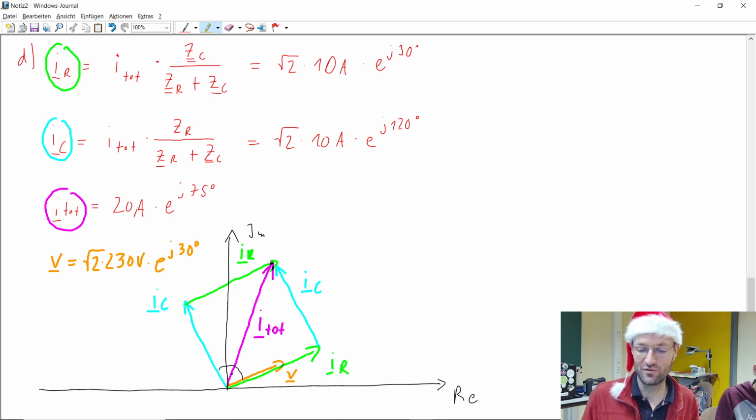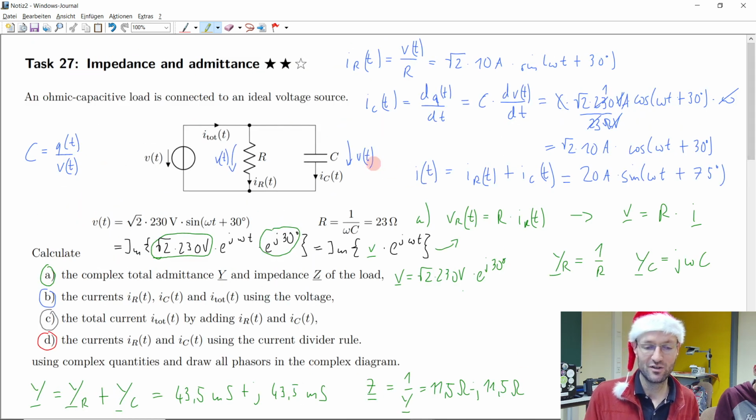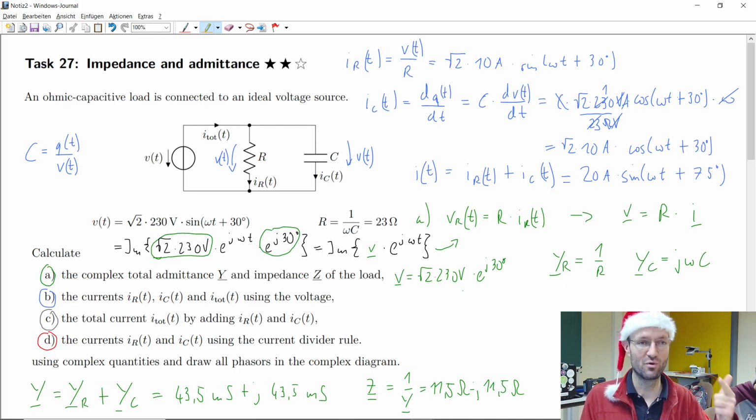And the advantage of this way, as said, is this allows us to calculate such circuits using exactly the same rules that we used before. So series and parallel connection of resistors will work, current and voltage divider rule will work, Kirchhoff's current and voltage law will work, all the superposition, branch current, mesh current, nodal voltage analysis methods will work.